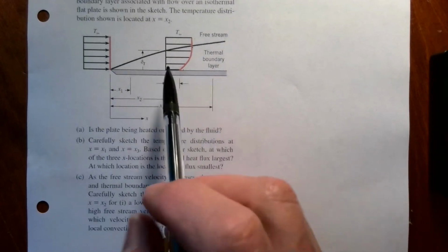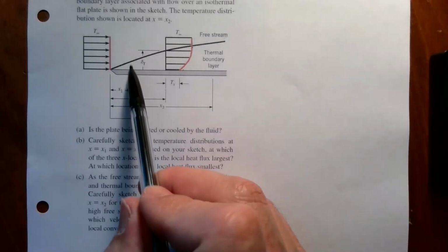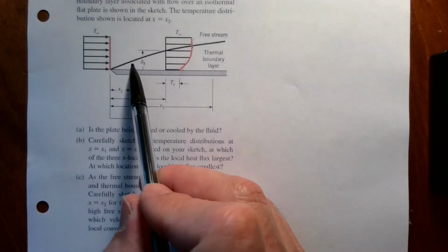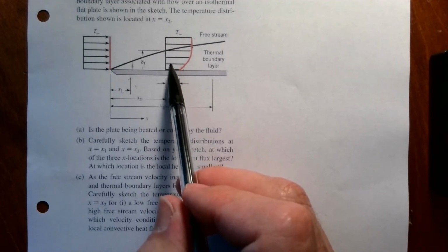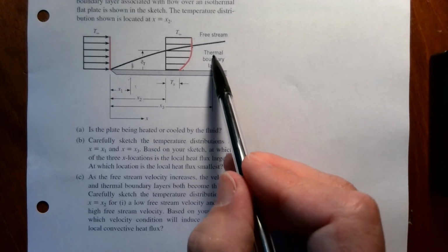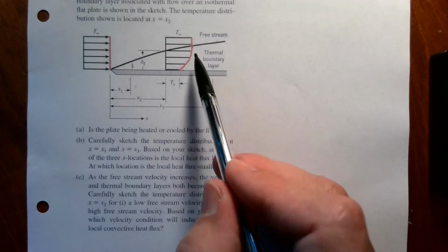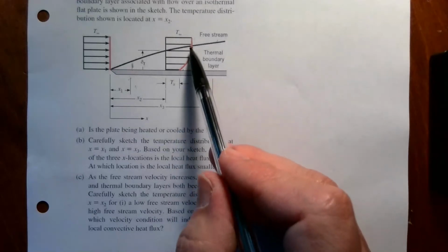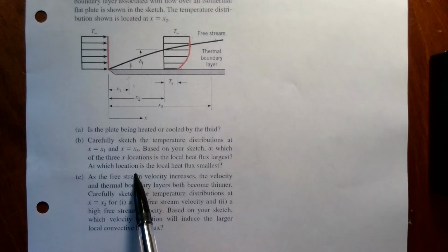positions 1 and 3. So we have a position x1 up here, right, where the boundary layer is very, very short. So over this distance, we have to vary from Ts to T ambient over that small vertical change. Here it happens over a larger vertical change. If you go down here to x3, you're going to draw it here as well. You go to an even larger change. That same shape, though, it'll look just like this same shape, just scaled up or scaled down.